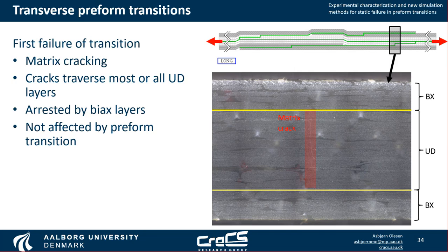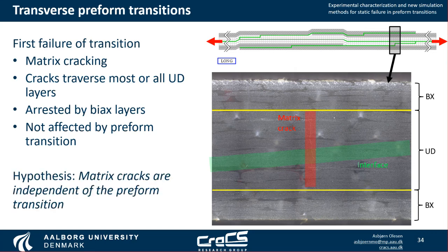What's more is that it doesn't appear to be affected by the preform transition, meaning that it doesn't kink or is arrested or grow in the interface of the transition. So this leads us to a hypothesis that matrix cracks are independent of the preform transition, which would be a good conclusion for our blade.